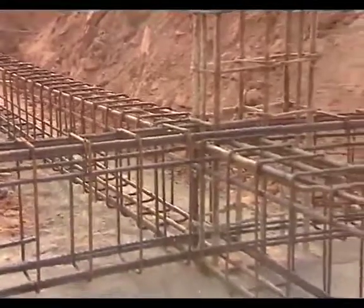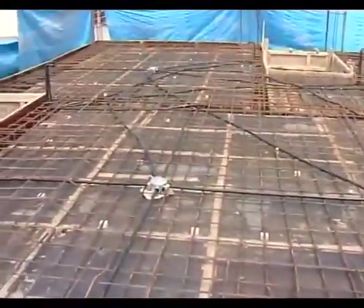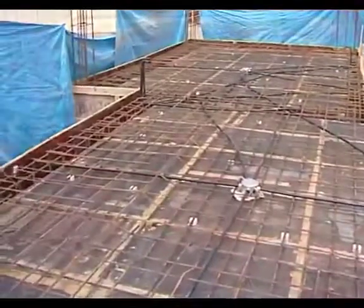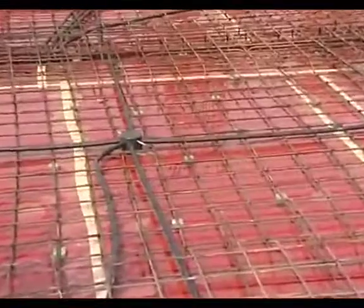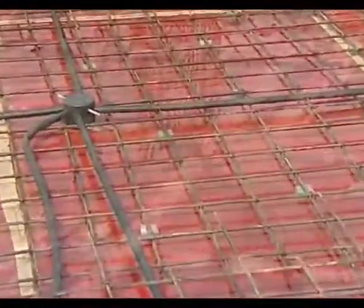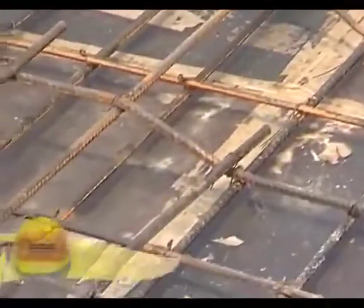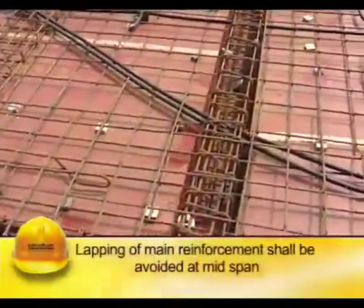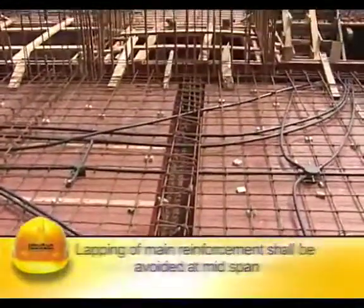The same importance for the number, position and spacing of reinforcement bars in slabs shall be given. The location of bending up the bars and proper tying, as well as provision of cover blocks and chairs for top rods, shall be inspected by a professional engineer before concreting. Lapping of main reinforcement in slabs and beams shall be avoided at midspan.